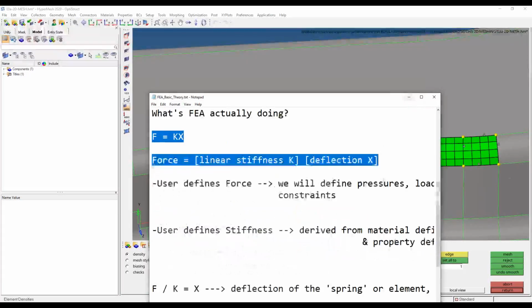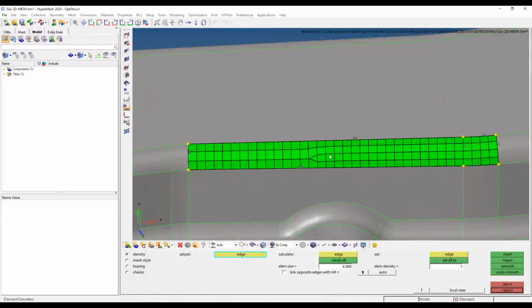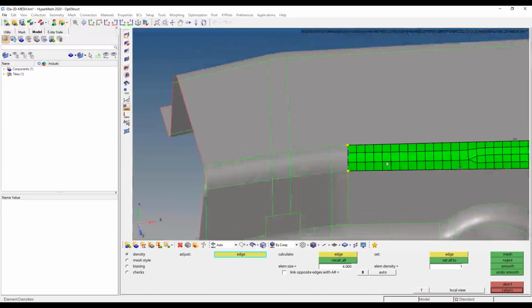So why I bring that idea up is let's come back to the fillet here. We're modeling half the fillet with 4 elements in the radial direction, the other half being modeled with 3. That's a big inconsistency right there. When I get to my results in post-processing, I wouldn't have as much confidence that the results on the left half correlate with the results on the right, knowing that they weren't meshed the same way. So what's great about HyperMesh is now that I have this penciled in, neon green view, to fix this, it's just a matter of zooming in.